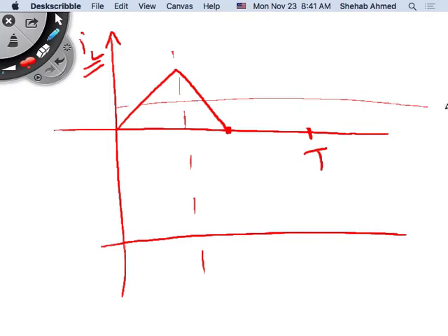But what is the physical phenomenon that we still cannot break? We cannot break the fact that the average inductor voltage has to be 0 in steady state, right? So we cannot change that. The average inductor voltage has to equal 0. So the voltage across the inductor here will be a positive number, and the voltage across the inductor here will be a negative fixed value, right?